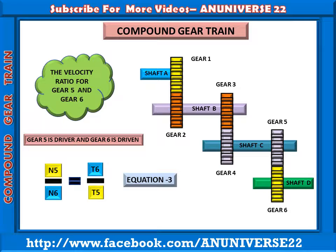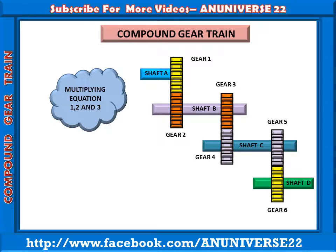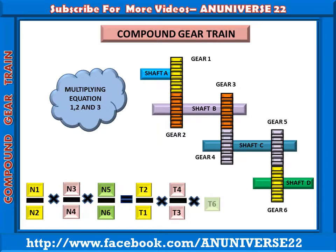Now for calculating the velocity ratio of the compound gear train, we multiply equations 1, 2 and 3. Then we get N1 upon N2 into N3 upon N4 into N5 upon N6, that is equal to T2 upon T1 into T4 upon T3 into T6 upon T5.